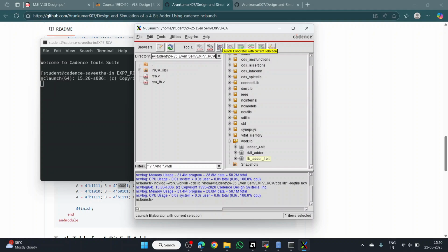That is the second step in the simulation process. Okay. Only if you click on this icon, this will be enabled. And just click on this. Yeah, again, the console will give the information about the process. If there is any red line in the console, that represents an error in the elaboration. If not, we can proceed to the next stage.